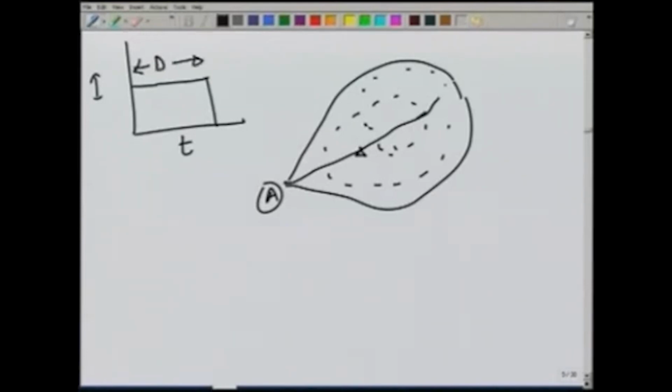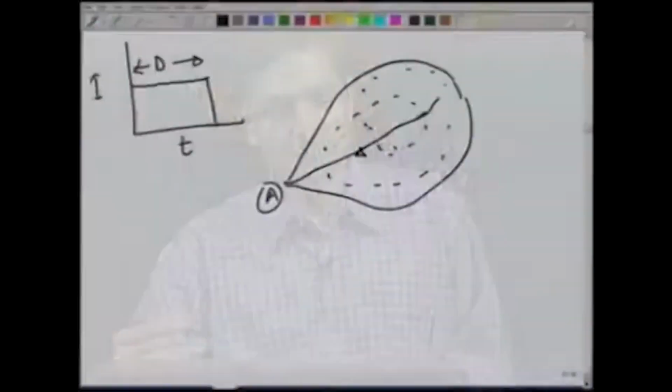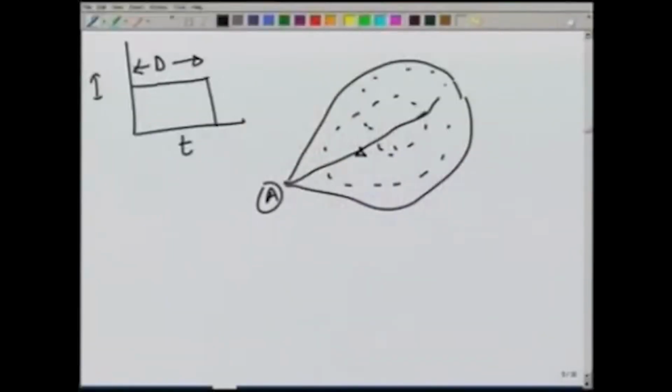Now, if this intensity is less than the evaporation and infiltration from the basin, then there will be no runoff. So, first it has to satisfy the evaporation, the infiltration, and also depending on the presence of lakes and other small depressions, the depression storage.